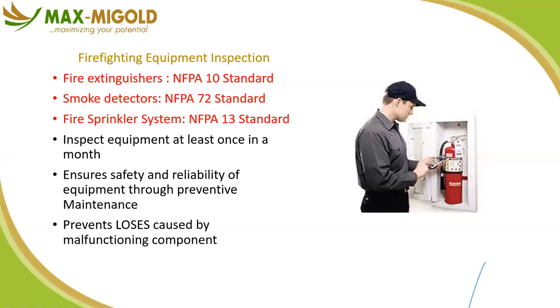This equipment, again, depending on your own personal risk assessment of your facility, needs to be inspected based on the frequency determined by you, but not less than once a month. We need to recap that. If the volatility or the risks that you have envisaged for yourselves mean that you should inspect your fire extinguishers every week, please do.